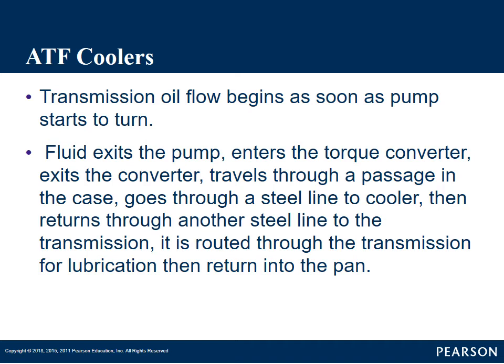It goes into the cooler on one end through a steel line, then goes through the cooler and back into another steel line where it goes back into the transmission. It is then routed through the transmission for lubrication. This is when all the parts of the transmission are lubricated.